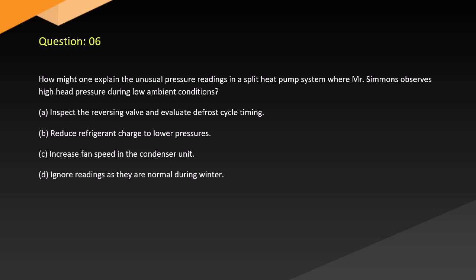Question 6. How might one explain the unusual pressure readings in a split heat pump system where Mr. Simmons observes high head pressure during low ambient conditions? A. Inspect the reversing valve and evaluate defrost cycle timing. B. Reduce refrigerant charge to lower pressures. C. Increase fan speed in the condenser unit. D. Ignore readings as they are normal during winter.